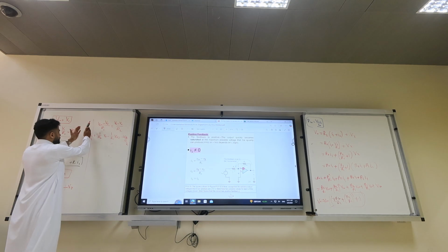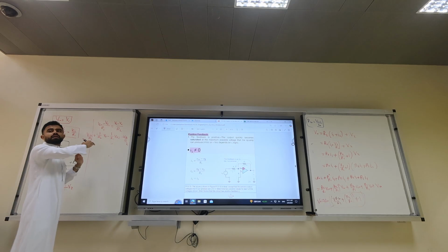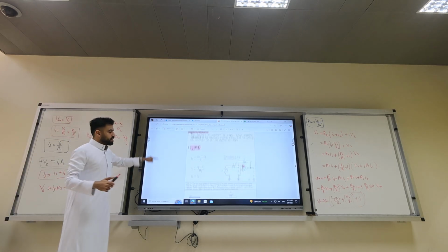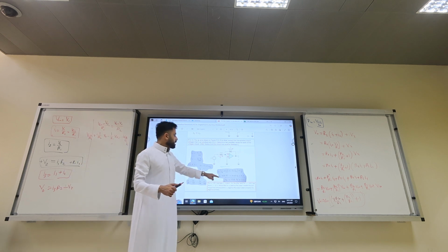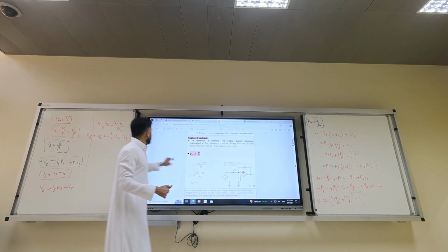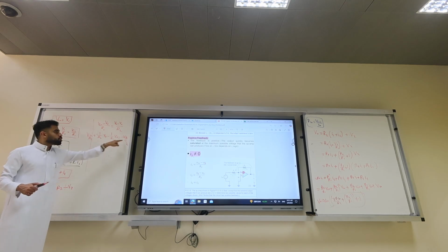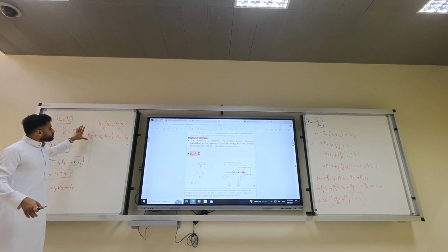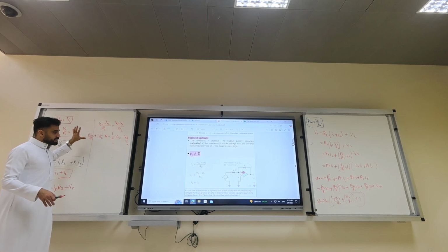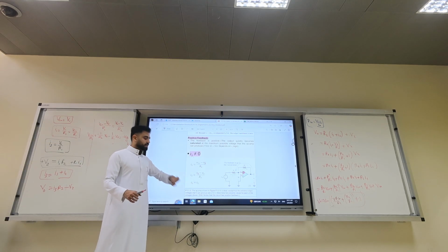The gain is, of course, positive R2 over R1 plus some components that lead it to saturation. And if you look at this example, try to solve it at home, you will find that you can find the relationship between Vx if you know V input. So, depending on how much input you provide, you don't know how much Vx. You don't know how much V output. You could be saturating at plus 10 or minus 10. In short, this is not straightforward. It's not favorable. The major thing you need to know is the output is saturated. We will do a numerical example next lecture.